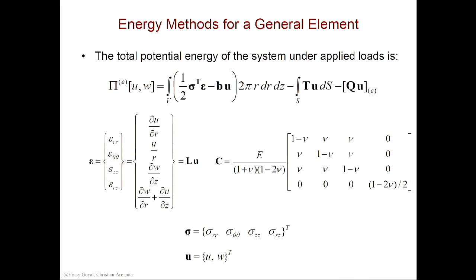If the hoop direction had no stiffness, can you pressurize a cylindrical pressure vessel very easily? Yeah, it will become like a balloon, right? It will deform infinitely. You need a hoop, like a band in that direction, stiffness in that direction, to prevent the radial expansion of that vessel, right? So that's why the hoop stress is important, and you will develop one. You will come up with a hoop stress, which we know for a cylindrical pressure vessel is PR over T. Okay, all right.